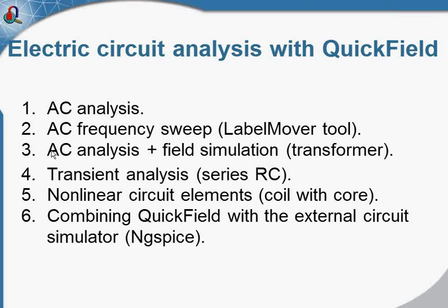And the third AC analysis case is the 3-phase transformer simulation, which includes both the field and circuit simulation parts. And the transient circuit analysis cases for today are the transient analysis of series RC electric circuit, the nonlinear circuit elements, the coil with the thermomagnetic coil, and the last example is the combining of QuickField with the external electric circuit simulator.